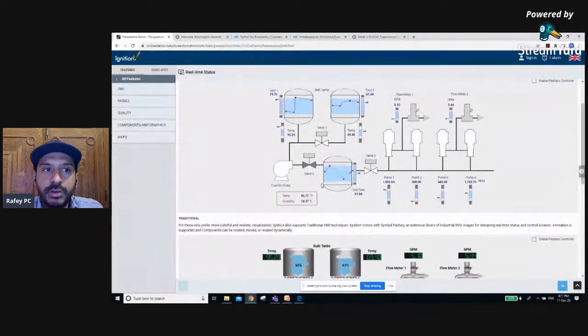So when you're looking at a screen all day long as an operator, you only want to focus their attention on certain things. You don't want to have a lot of colors on a screen because this is not a movie or a video game. This is critical infrastructure. So you only have high colors where needed.